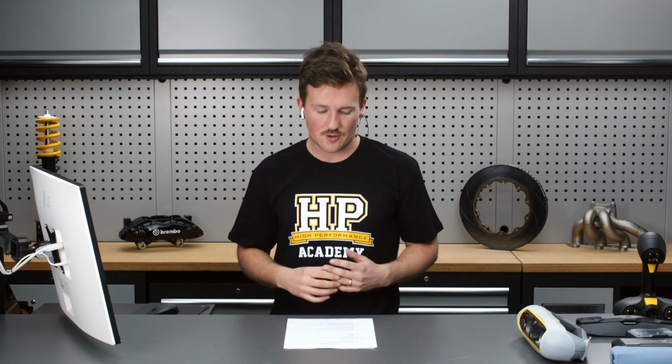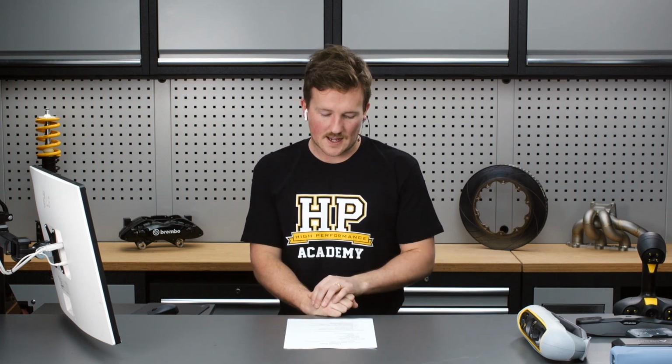So again, for something like scanning a small mechanical part, we might want to increase that resolution to under 0.5 millimeters. But for something like a large body panel, maybe 1 millimeter or even up to a few millimeters might be okay. And that's usually adjustable in these dedicated scanners. But in something like an iPhone using photogrammetry, for example, we can usually only expect a lowest resolution of around a few millimeters or so, and it's probably not going to get much better than that in most cases.